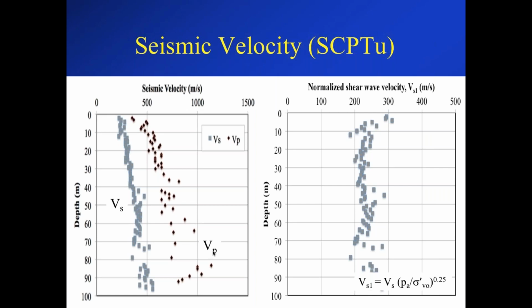But on other projects, when they stack it in layers, it can create what I've termed fines-dominated and non-fines-dominated regions. Where you've got significant weathering, where the parent rock breaks down and becomes more clay-like, you tend to see a more clay-rich deposit, and others less clay-rich, hence fines dominated and less fines dominated. So hopefully that answered that question.